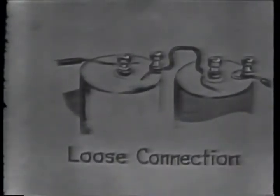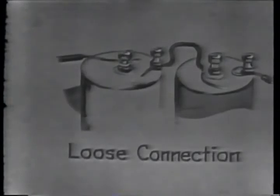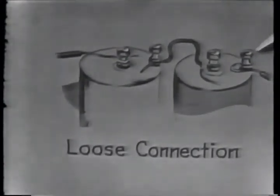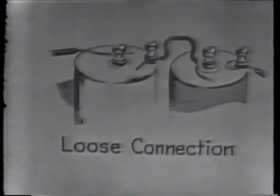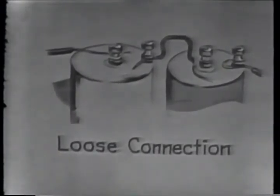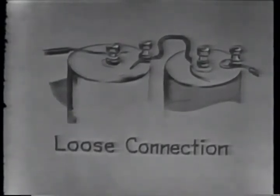First, let's consider some examples of open. Here are some troubles that could cause an open. This one is a battery with loose connections. Most of the time, a loose connection is the same as no connection, which is the same as an open. Any circuit component with a loose connection opens the circuit and stops current.